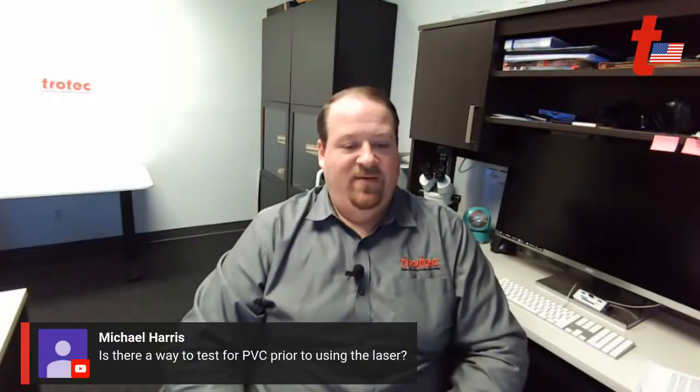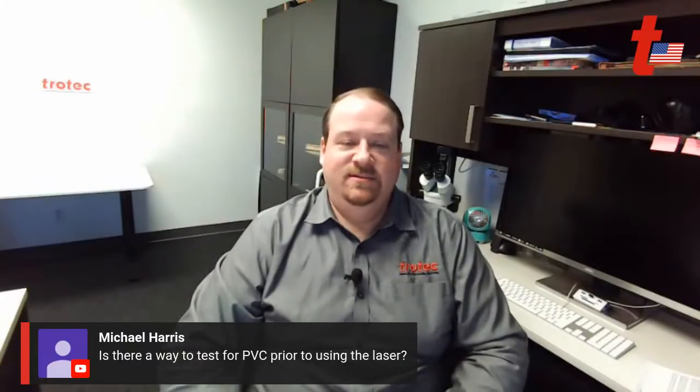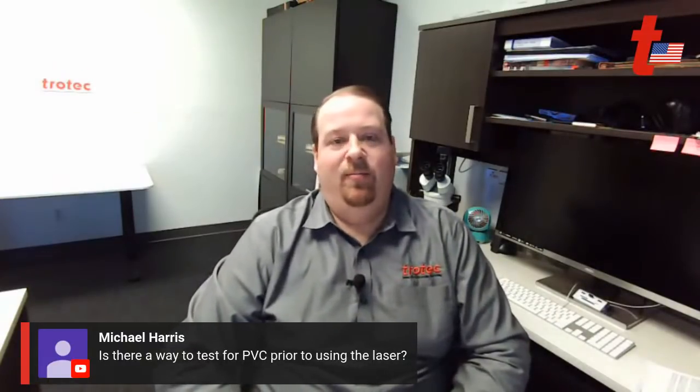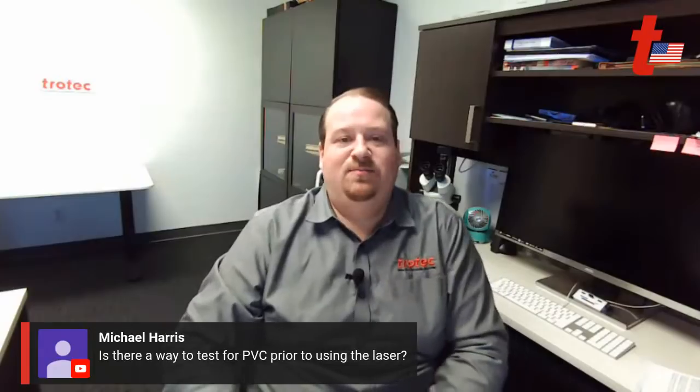Is there a way to test for PVC prior to using the laser? No, not unless you've got a chemical lab. My suggestion for people is PVC is not going to destroy your laser in one shot. It takes a cumulative running of PVC to actually cause damage to your laser system. My suggestion is to run it at least once on known PVC.